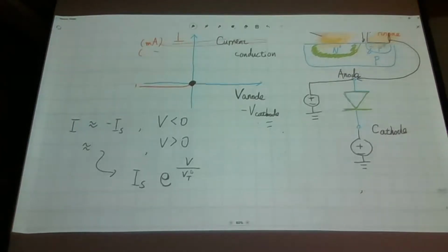That is the approximate form of our IV characteristics in this forward biased diode. So then maybe you feel, oh, that's so simple. I expected a very complicated functional form, but I'm just saying that it follows exponential dependence. So if you increase your voltage, then what happens? If you increase your voltage, then the argument of your exponential function is increased too. So you will have a larger number from this exponential function, so your current will be increased.